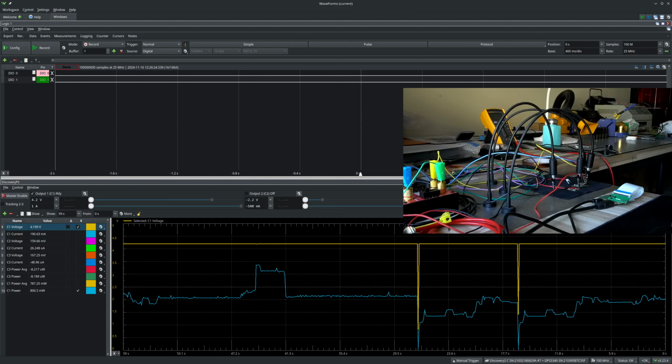Hi, so today I wanted to talk a bit about analyzing MIPI DSI display initialization, particularly for displays which you may not have documentation for and you still want to reverse engineer and use. So for example, I have this 6-inch flexible OLED panel from BOE. It's 2880 by 1440 pixels, and it has a standard 4-lane DSI interface.